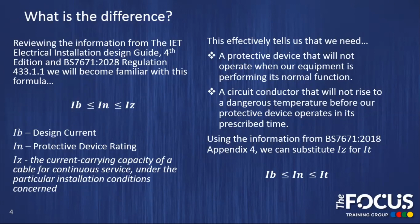From reviewing the information of the IET Electrical Installation Design Guide and BS 7671 Regulation 433.1.1, we will become familiar with this formula. IB, the design current of our circuit, should be less than or equal to IN, the protective device rating, which in turn should be less than or equal to IZ, the current carrying capacity of our cable for continuous service under the particular installation conditions.